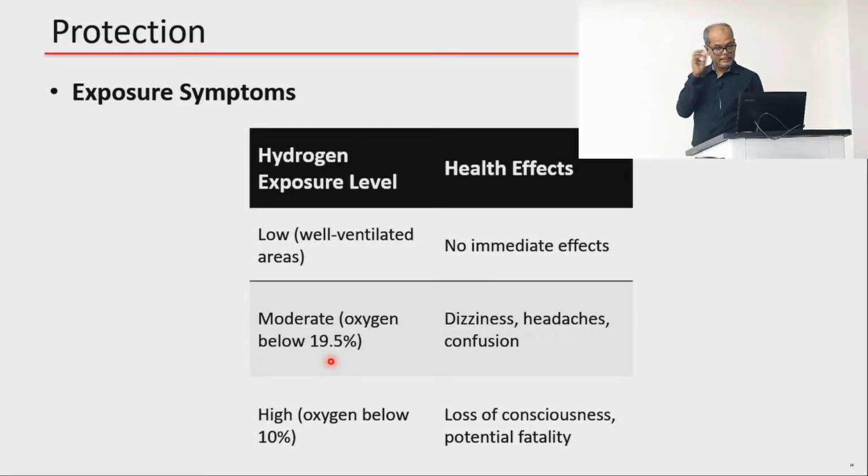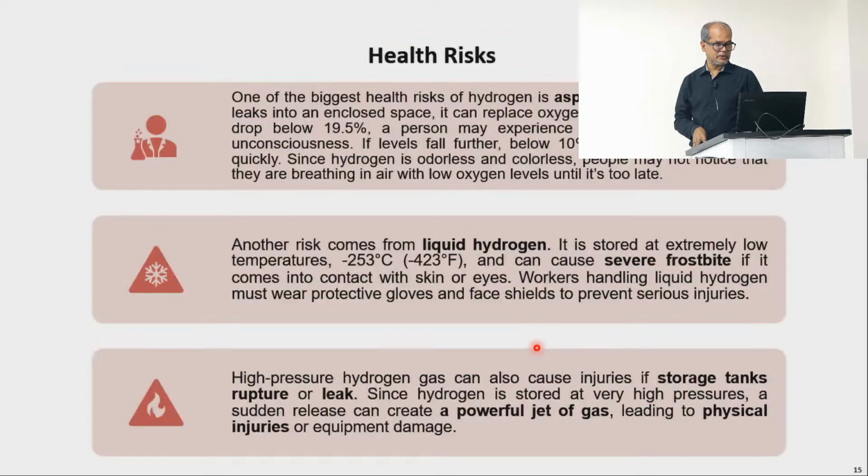So, if there is a leak or something like that, the oxygen can go to a very minimum level, and that can produce headache, dizziness, and sometimes loss of consciousness, which can bring potential fatality as well. So, we need to check the oxygen level if you work in a very confined space with hydrogen.